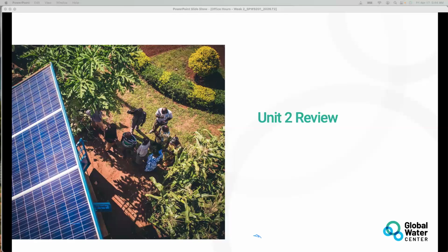If the formation shows there is no porous media, like clay or some other kind of formation, we put blind casings. In such a way, the casing arrangement will be done during installation. This is totally clear for me. So I take the schematic given by the Global Water Center as a general one. Okay, thank you very much.